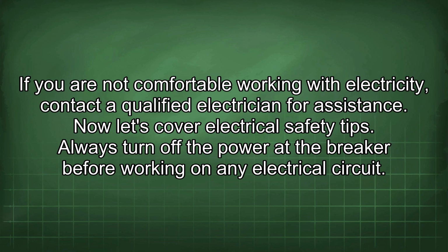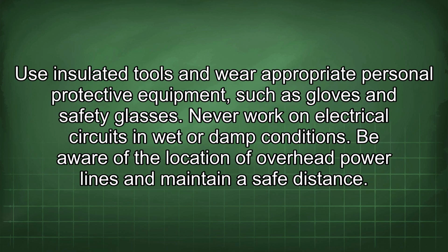Always turn off the power at the breaker before working on any electrical circuit. Use insulated tools and wear appropriate personal protective equipment, such as gloves and safety glasses. Never work on electrical circuits in wet or damp conditions. Be aware of the location of overhead power lines and maintain a safe distance.